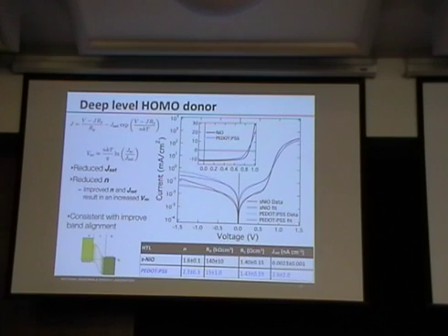How many people have read that and buy that? How many people have read Shockley's paper? Shockley-Read-Hall's paper. So I would encourage you to do that. But what I will say is that one thing that we're assuming, when we think about ideality factors between 1 and 2, is an ideal diode, which has along with it a lot of caveats, as outlined in those papers.